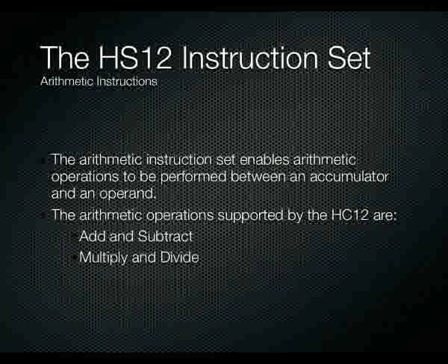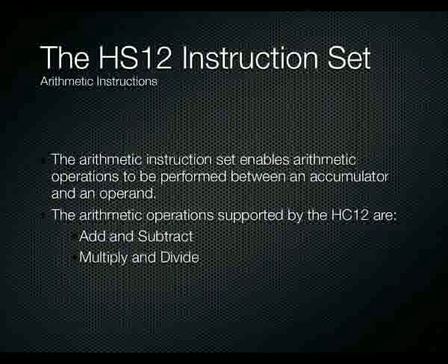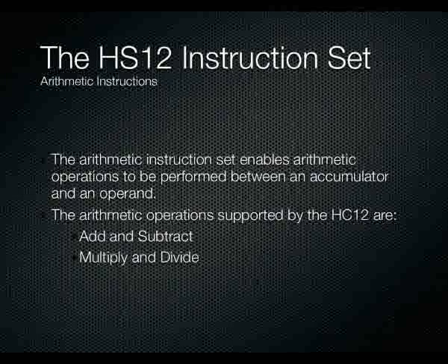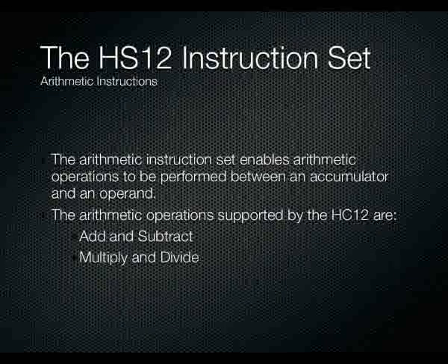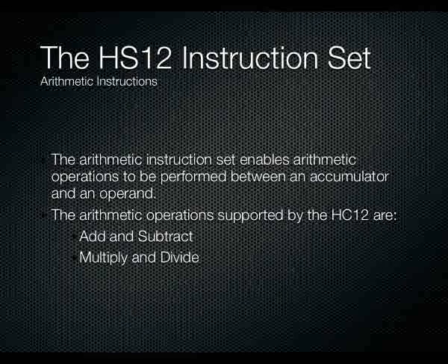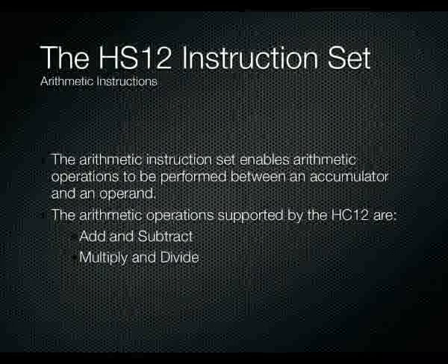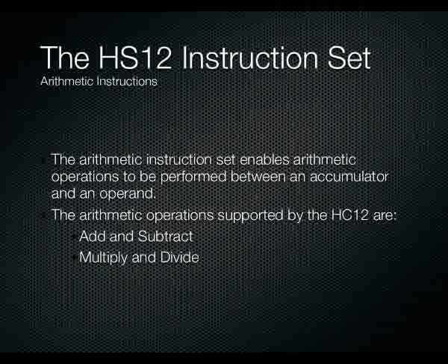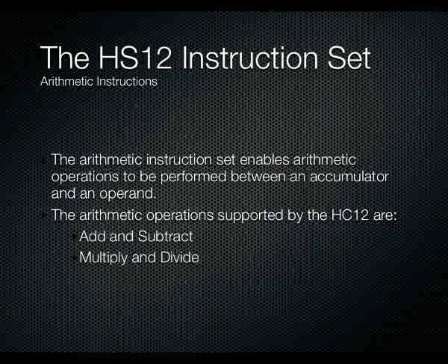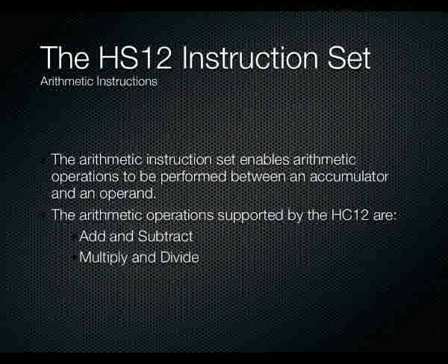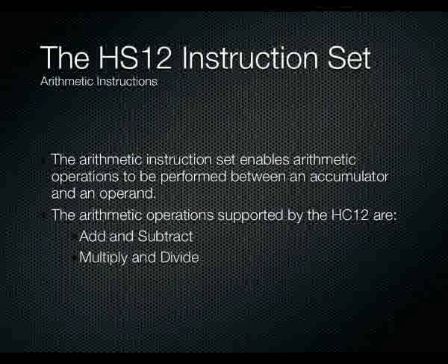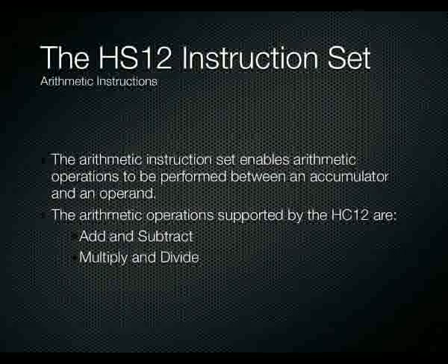We're able to perform many mathematical operations, and the basic ones at our disposal are add, subtract, multiply and divide. We perform these instructions using an accumulator and some other operand, whether it comes from another accumulator or from memory. It depends on which instruction and which addressing mode you're using. So the primary operations we have on the HS12 are add, subtract, multiply and divide, the four primary operators.